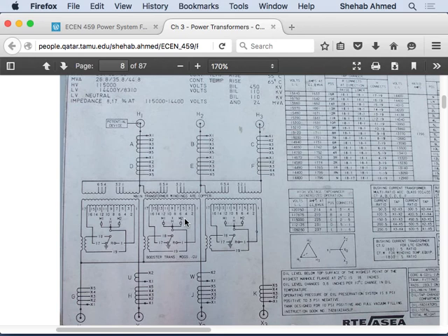And you will have colors and numbers, and we will normalize numbers on the voltages and currents around the system for us to be able to sit back, look at a big power system and say, okay, there's a problem in this region, right? If you have a big power system map in front of you and you see the voltage there being 15 kilovolts, you have no clue if this 15 kilovolts is good or bad, right? But if we find a way, and we will do that in this chapter, to normalize quantities around the power system, such that the normal is 1, right?